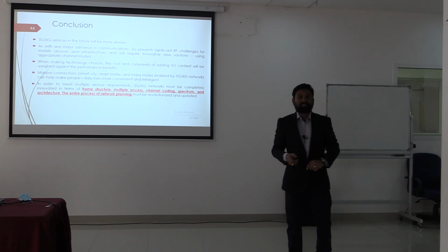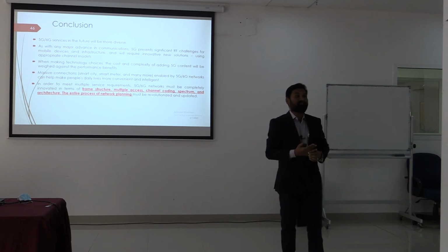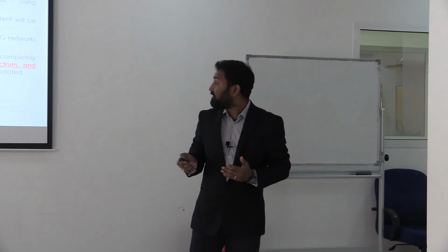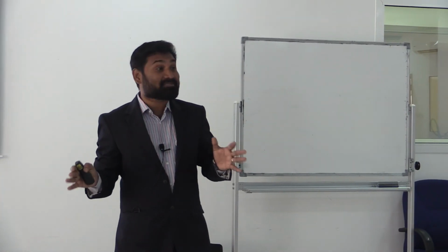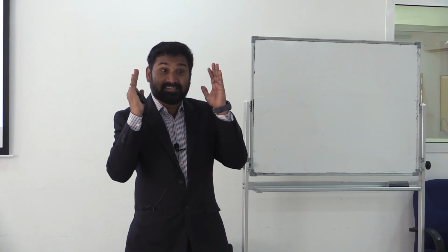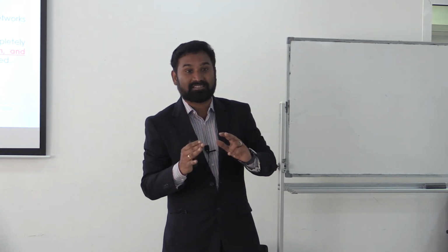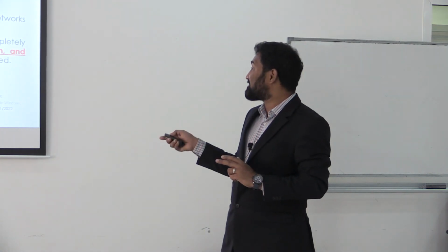So let us come to the conclusion. So far I have given an overall insight about 5G techniques, 5G technology and the corresponding channel models. Still it needs to be analyzed in terms of various frame structures, multiple access techniques, channel coding and spectrum. Here we are assuming the transmitter and the baseband communication systems are already developed. Then we are checking only the electromagnetic characteristics of the channel behavior with respect to millimeter wave frequency and the midband frequency. But we still need to analyze the baseband in terms of frame structures and multiple access.